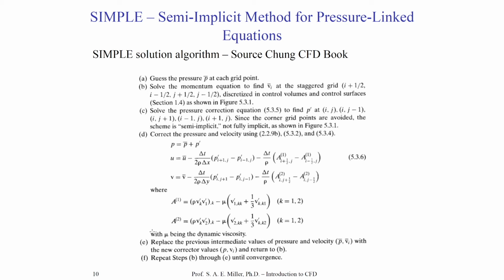This is a simple implementation of the 2D incompressible SIMPLE algorithm, which can of course easily be extended to 3 dimensions, and there's many papers written about this. So when you select the SIMPLE algorithm in the CFD code, which are usually commercially based to solve incompressible flows, this is the algorithm that's actually solving the equations we're looking at. Note this does not contain a turbulence model, and these equations can become much more complicated if, of course, we use this SIMPLE algorithm with a particular turbulence closure. So make sure that you understand that.